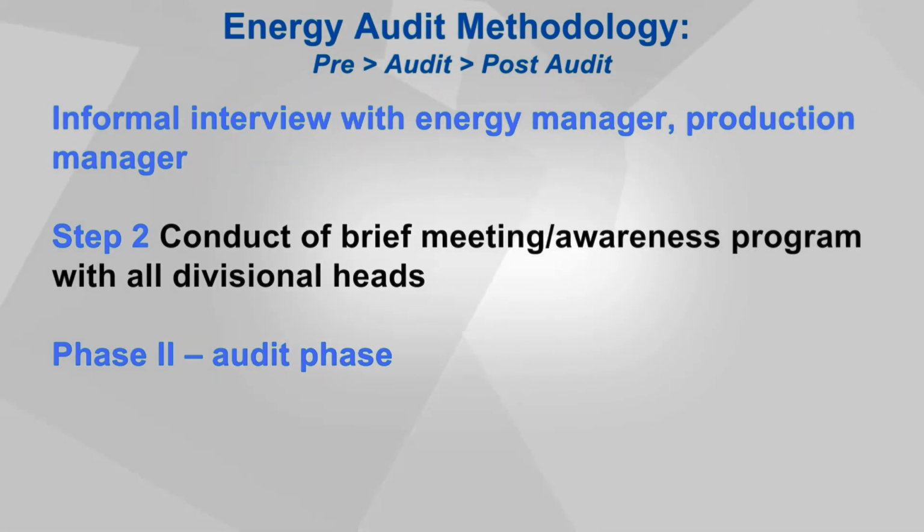Gathering preliminary data. Relevant data is collected prior to the on-site audit to gain a better understanding of the facility's energy consumption patterns. This data may include utility bills, facility drawings, equipment specifications, production schedules, and any existing energy management plans. Next one is conducting a kickoff meeting.